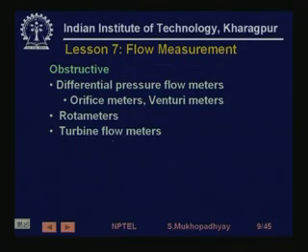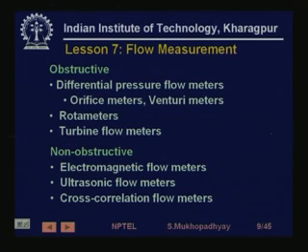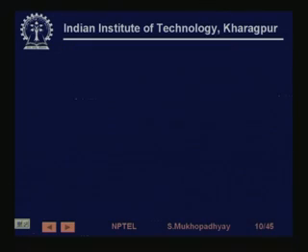So, flow measurement is a very important component of process control. We talked about the obstructive methods of measurement, including differential pressure flow meters like orifice and venturi, rotameters, turbine flow meters. We also talked about non-obstructive methods like electromagnetic flow meters, ultrasonic flow meters, cross correlation flow meters and things like that. After flow measurement, we